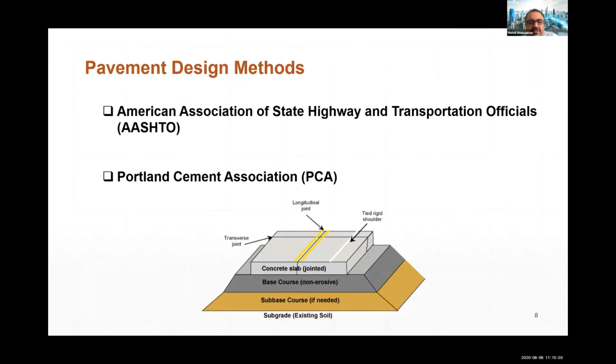This empirically based pavement design procedure is used by many practicing engineers worldwide. The AASHTO guide is based on the performance of the test sections under truck traffic and environmental conditions. One major output of the AASHTO road test was the load equivalency factor.